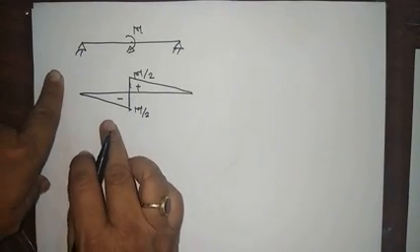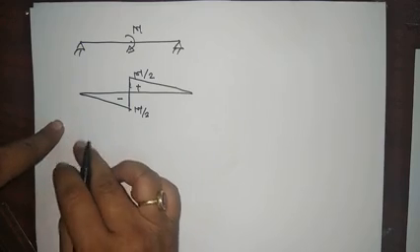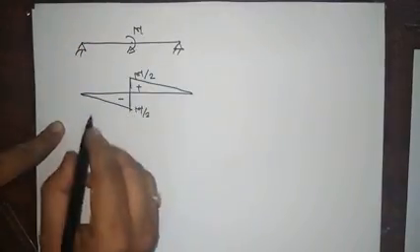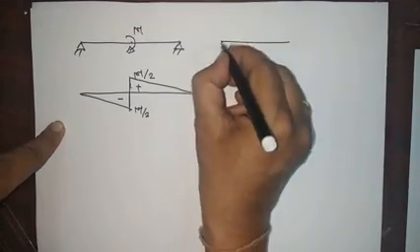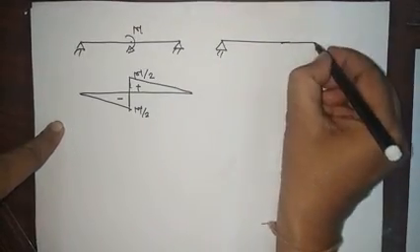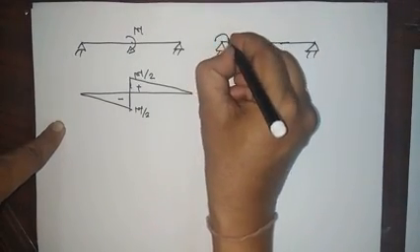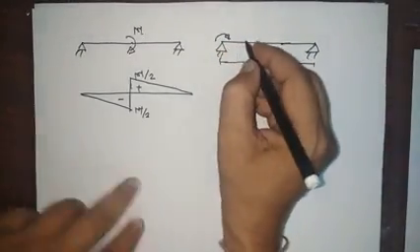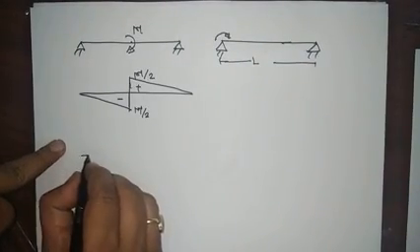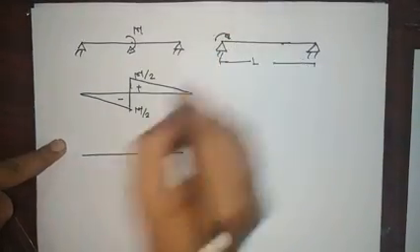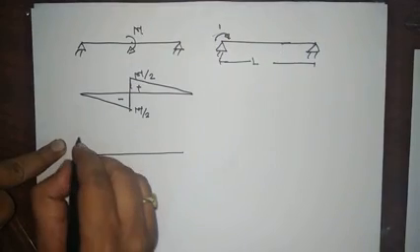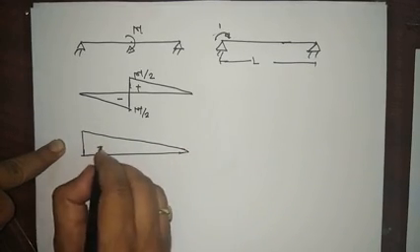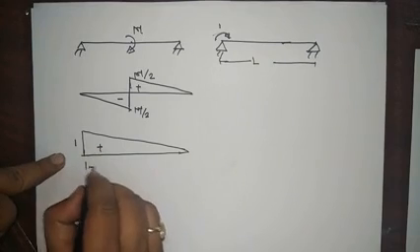Now the next step in the diagram multiplication method is to draw the bending moment diagram for the rotation at 1. So we are applying a unit moment at coordinate 1 and this span is here. So for this the bending moment is here. This creates sagging bending moment. And it is 1 unit moment. So this is positive, and this height is 1, this length is L.